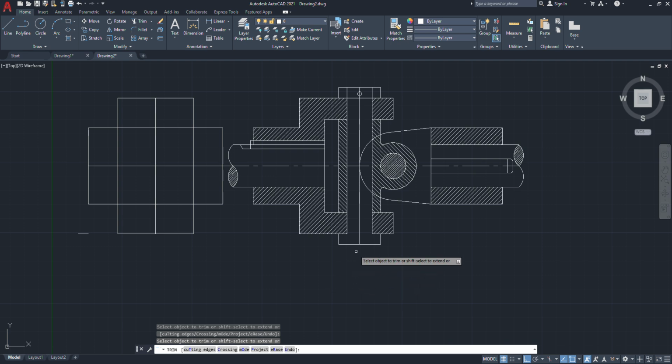We will do one thing, we just copy this collar. Here we want to do two circles, circle here this point as center and radius is equal to same, 30 mm diameter, 15 mm radius, and one more circle of this much diameter.